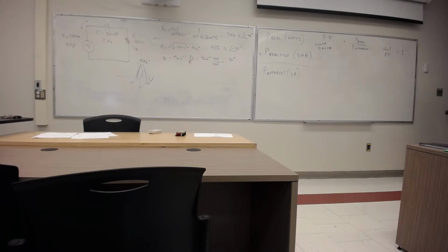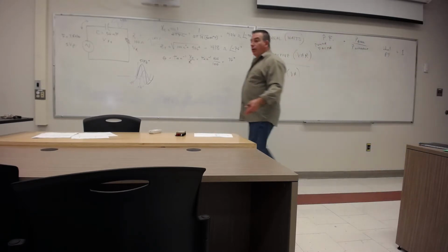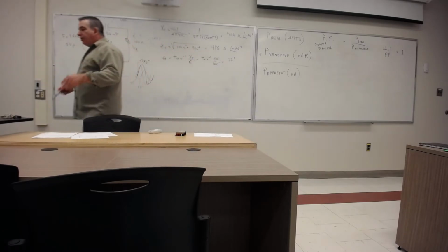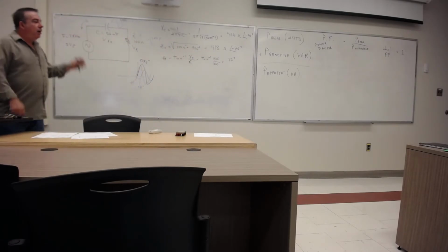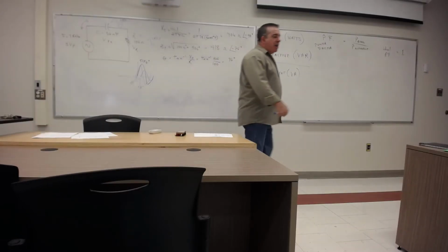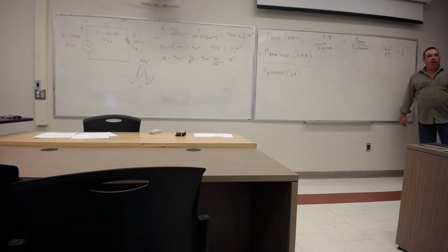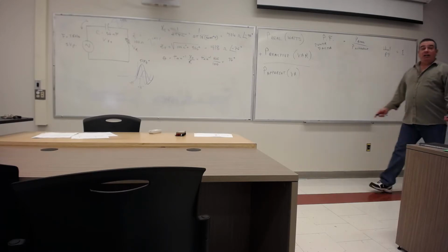And that's going to be one of your big responsibilities as an electrician. Wherever you're working, in your shop, wherever you are, one of the big concerns is going to be that we've got to have a power factor of 1. The reason is, when your power factor is lower, you've got some reactive power running around in your system. And that's not a good thing. It's wasteful.